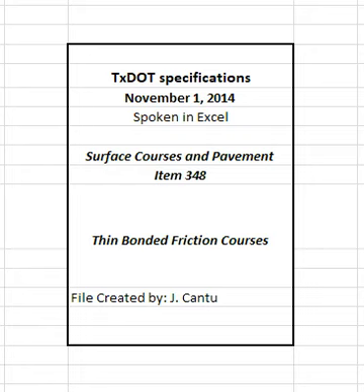4.9.5 Miscellaneous areas. Miscellaneous areas include areas that typically involve significant handwork or discontinuous paving operations such as driveways, mailbox turnouts, crossovers, gores, spot level-up areas, and other similar areas. The specified layer thickness is based on the rate of 90 pounds/square yard for each inch of pavement unless another rate is shown on the plans. Miscellaneous areas are not subject to thermal profile testing.